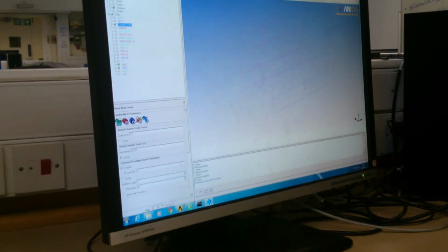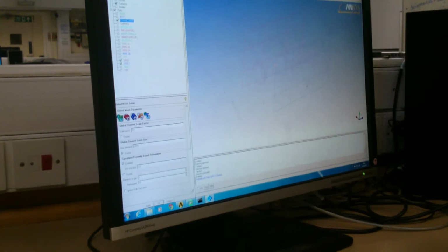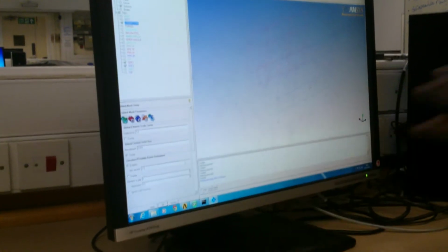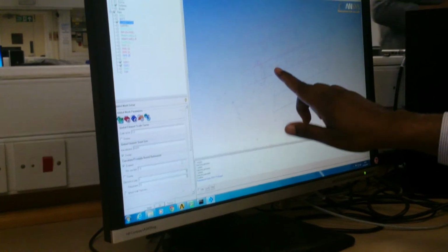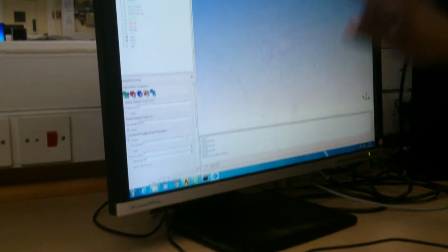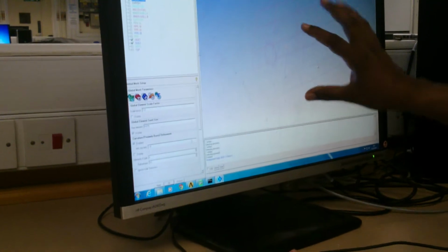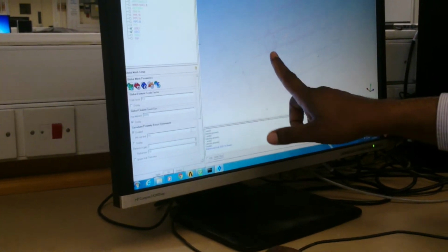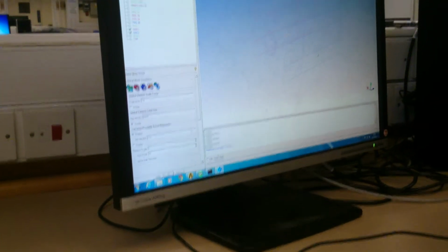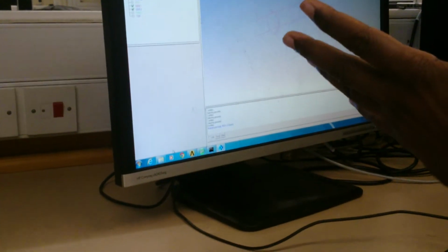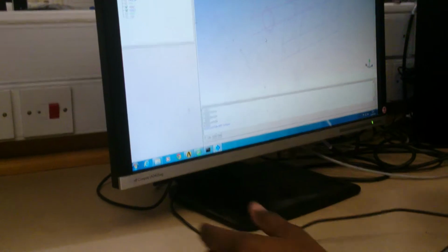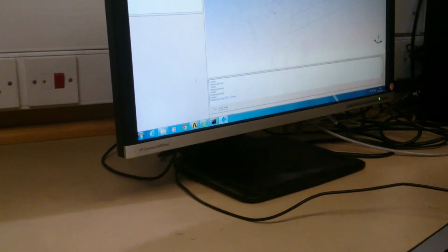Right? So the global one is basically what the global means what? It's going to mesh the whole geometry, all surfaces with elements as large as this one. But deep there, this could be adequate to this part, but it's not adequate to this part. What would you do? You will accept this as a global. Now you know the surfaces which need to have a finer mesh, right?